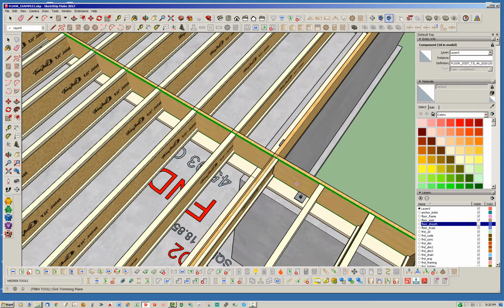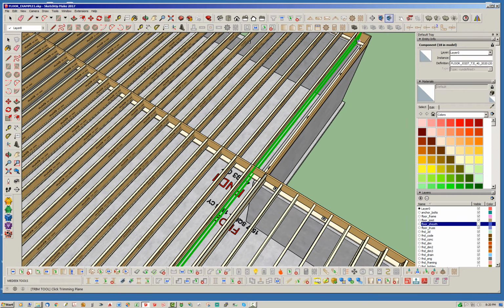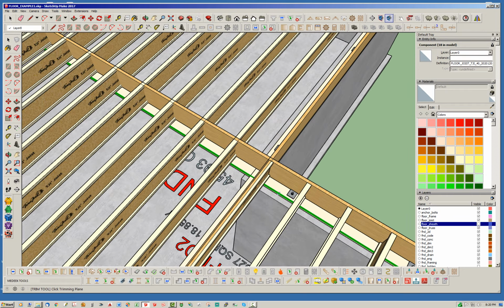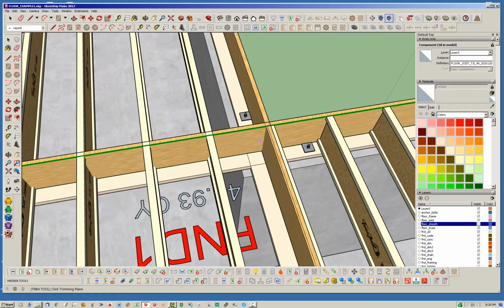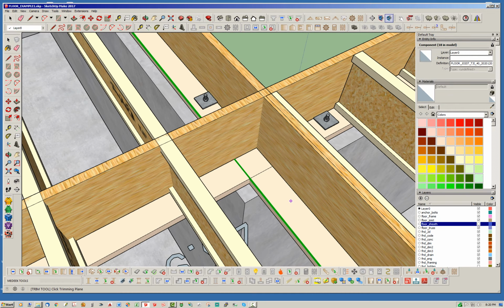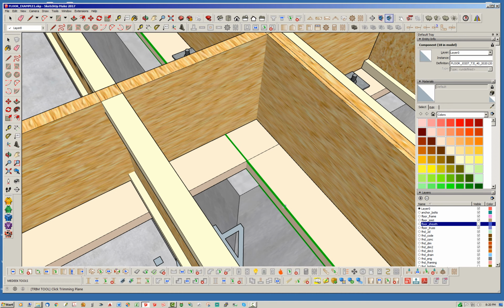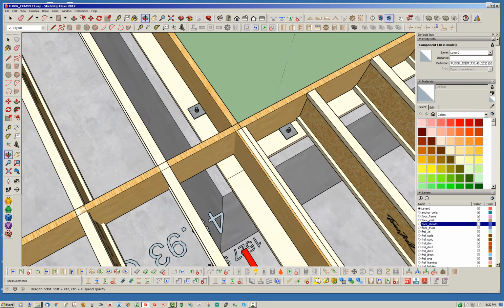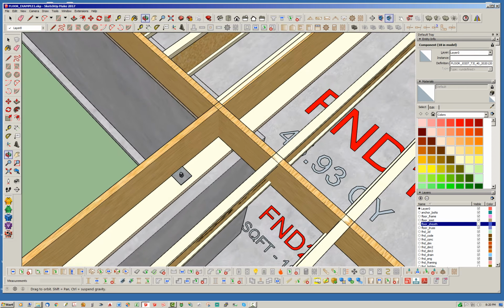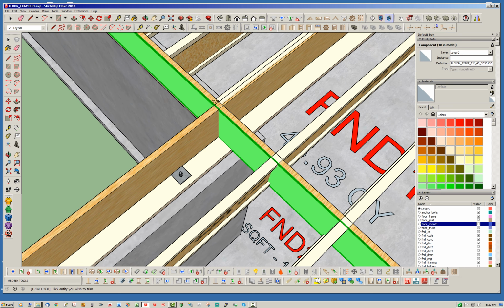Okay, so which way do we want this to run? These members are coming that way, so let's have this member be the long one that overshoots. We'll select this face here, then select that member, and then this guy. Escape key, hit that. Now we're going to trim off this member. And let's see, this member, I think.